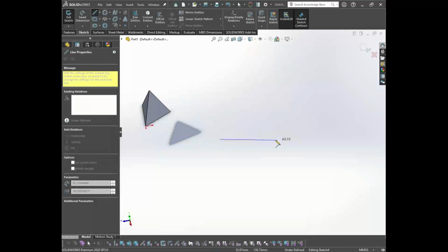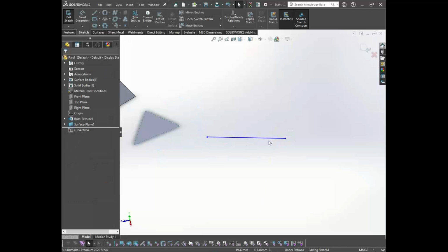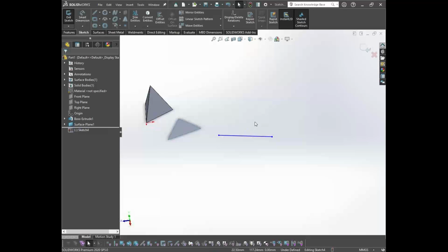It will look like this. There will be 2 nodes at the ends and 1 element in between. Since my structural member is going to have a uniform cross-sectional area throughout its length, we can consider the beam elements. The section properties will be considered in the back end of the problem, and those won't be displayed to us on the screen.